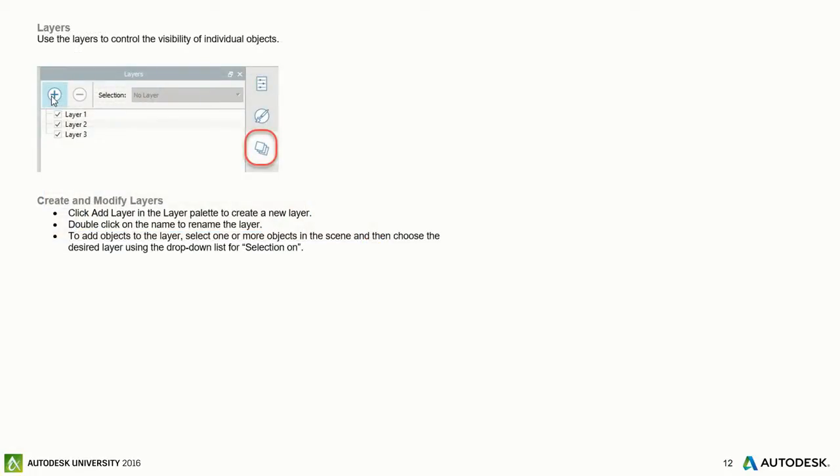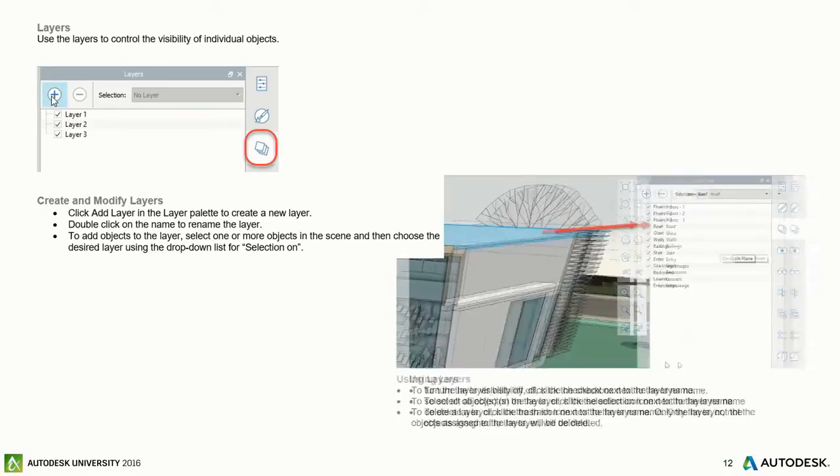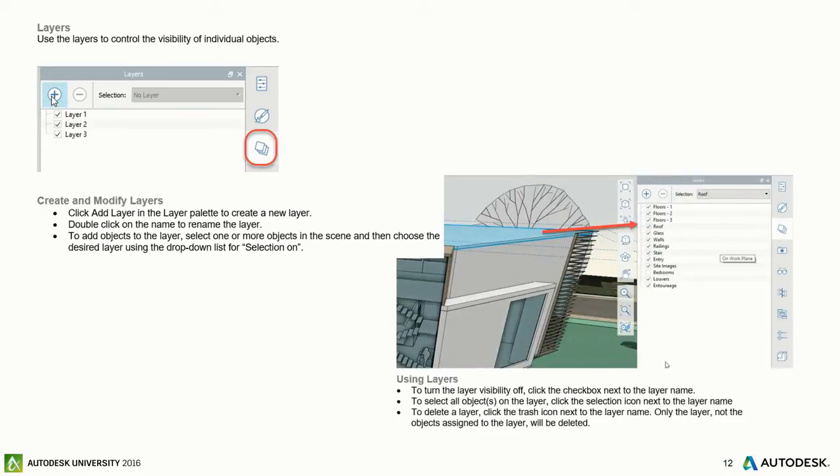Layers, obviously, just like SketchUp, we have layers in here. When you draw things, nothing gets put on a layer. So there's nothing like, of all things, I'm going to bring up AutoCAD, there's no such thing as layer 0. Okay? When you draw things in FormIt, it's just on no layer at all. So it's up to you, as you want to do visibility control, either for yourself or through your scenes. It's up to you to pick on that information and put it on the correct layer, and then you have the control over turning it on and off whenever you want.